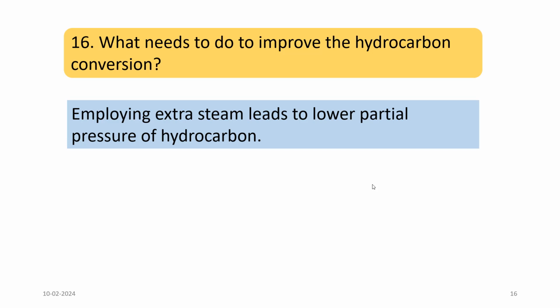So here extra steam is added to the reactor so that a lower partial pressure is maintained, and that will improve the hydrocarbon conversion.